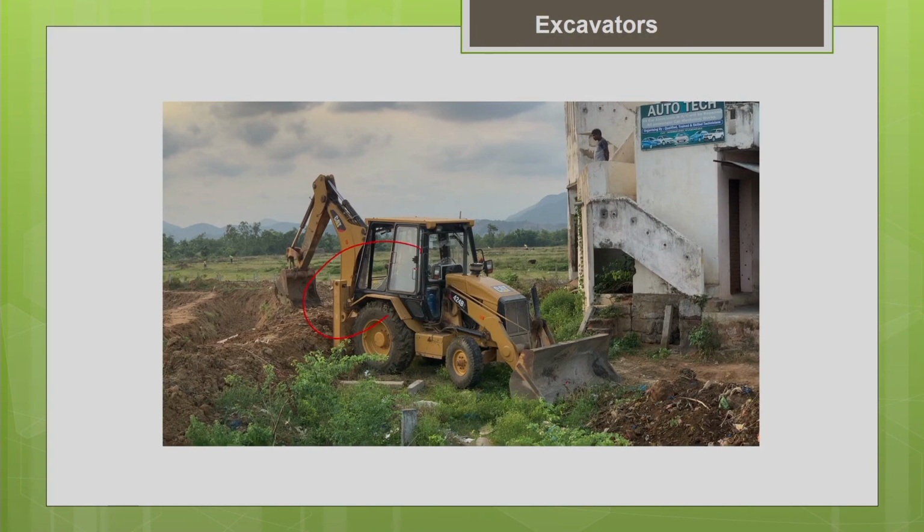So this is a wheel mounted loader. You have to carefully note that you have to extend this outrigger. You can see this outrigger, right. This outrigger you have to completely extend on both the ends and make sure that the load is transferred from the outrigger to the ground. This is very important from the stability point of view.